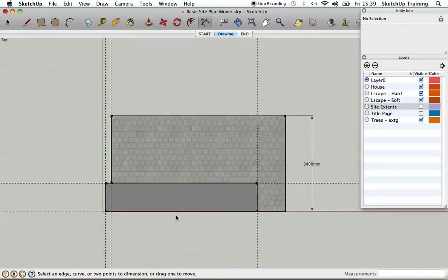So then what do we need to do? Then we start to think, well actually we're going to give you some text, weren't we? Two ways we can easily use text. We can use the text tool we added on the toolbar. We can click on it, and drag it out, and we then start to create something that's got what they call a leader line, a dimension line. It's a leader line because it's a text. And here we could type in patio.